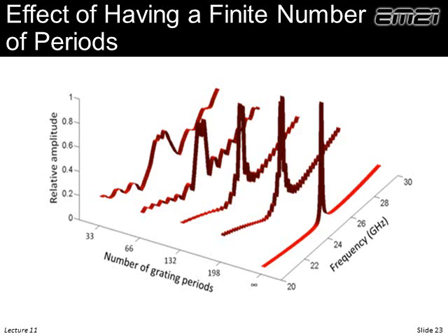The other thing we could ask, we describe the guided mode resonance filter as a wave hits a grating, it diffracts, that can couple energy into a guided mode. That guided mode then propagates down the waveguide, it sees the grating and it slowly leaks out. Well, it has to leak all the way out in order for it to interfere with the applied wave. So one could ask, how long do these guided mode resonance filter devices need to be so that our performance approaches something useful, or that of an infinitely periodic device?